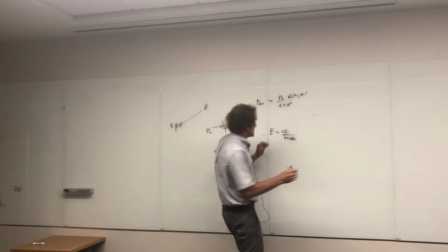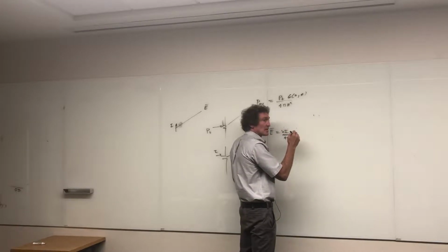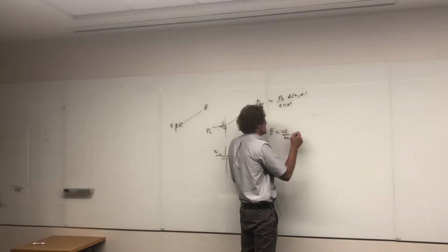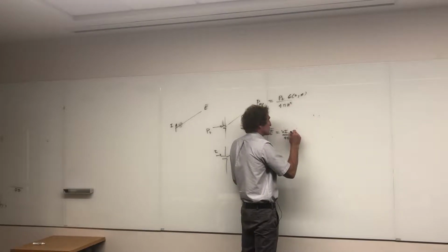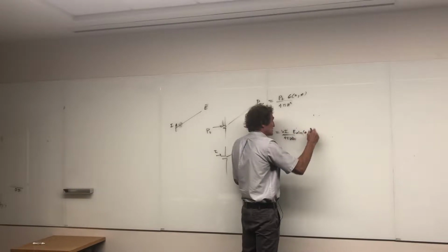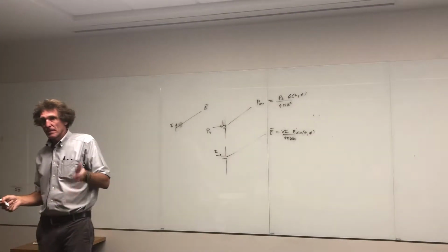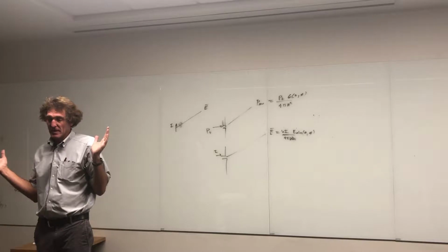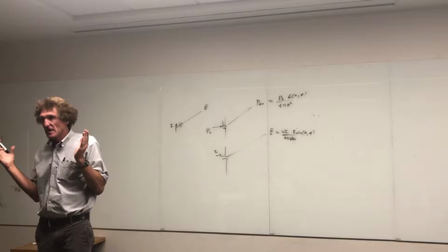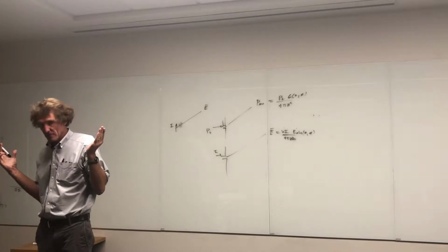Now, when you take this and you multiply it by the square root of the gain, call it the electric field pattern, then instead of gain here, you could put in the actual element's electric field pattern of theta and phi. So for a dipole, it would be sine theta, right? For a half-wave dipole, it would be cosine of pi over 2 cosine theta, over sine theta, right? In other words, that's a function of angle and a function of the length of the antenna, or the shape. Follow me?